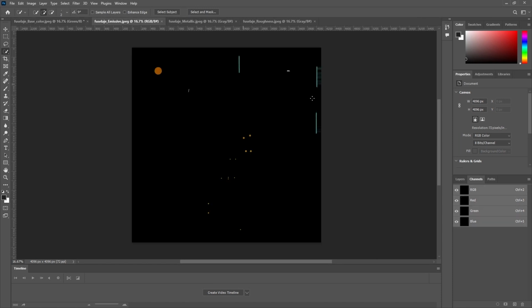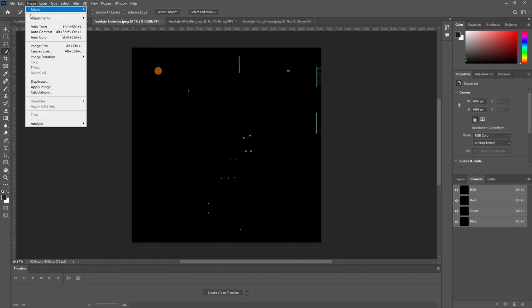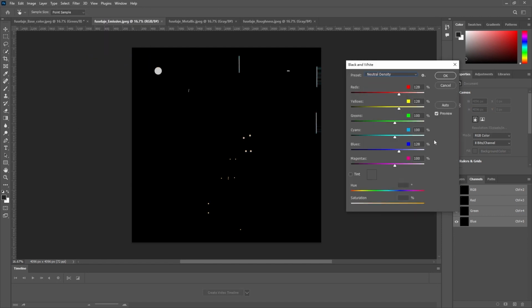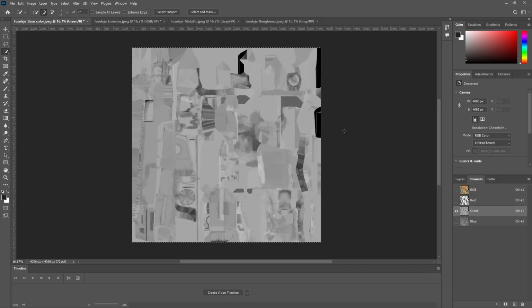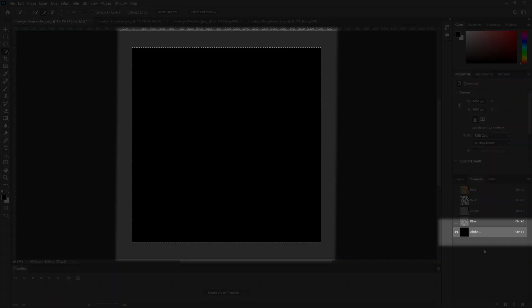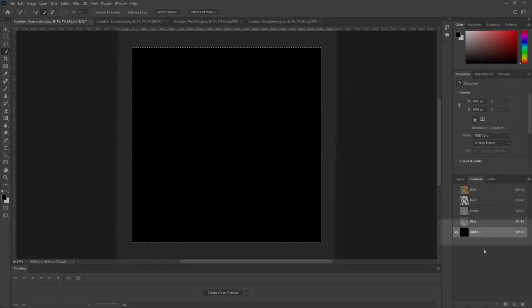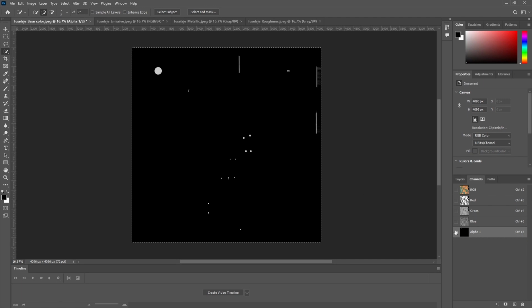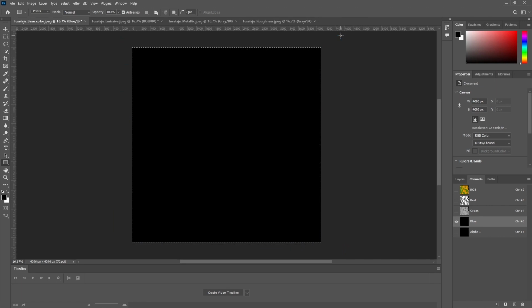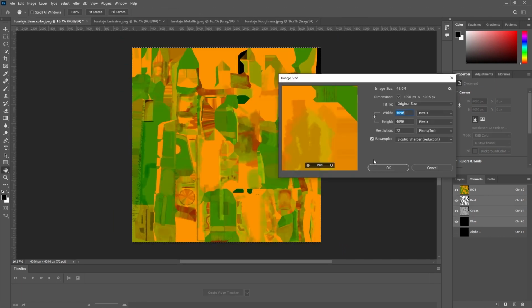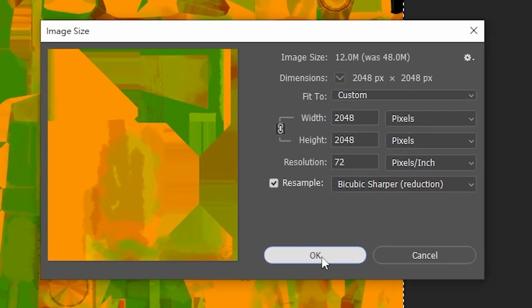The emissive map usually uses full colors. However, No Man's Sky only uses the alpha channel of the texture for the emissive map. Tweak the map so that it is in grayscale. To transfer the map to the canvas, add a new channel to the canvas, isolate it, and copy over the emissive map. Finally, color the blue channel black, as it will not be used by the material. Resize the texture to your desired dimensions.